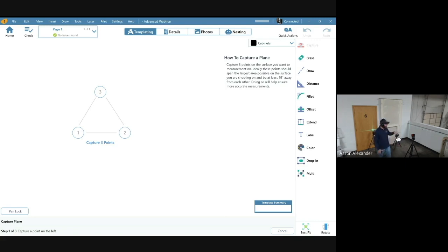So you see here, I've got a couple of different lasers with me. I've got our standard Lino L2, which gives us our level and plumb, as you see in red right here. And then I have another Leica laser over here, which is putting out 3 laser lines that I'm going to talk about for these returns. Not necessarily mandatory for doing this, but we just started playing with these, and they're definitely helpful in establishing these planes on these smaller returns. That's really where it's going to help you out a bunch.